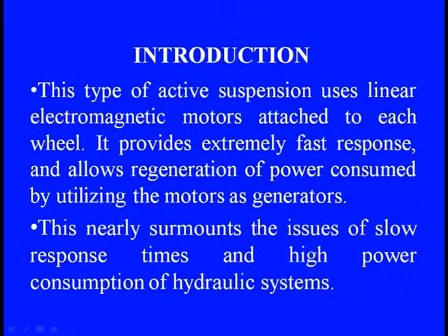And these electromagnetic devices like the motors provide extremely fast response, because the response time is very low in these types, and they allow regeneration of the power consumed by utilizing the motor as a generator. So one important feature of these electromagnetic motors is that they can absorb the energy even at resonance, and whenever required, these motors can act as the generator, through which we can reutilize the energy or power consumed in those devices.